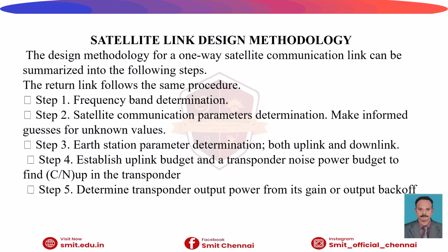transmitter. The uplink free space loss also should be monitored, as well as the atmospheric loss, the rain loss, and the satellite receiver gain, which should be measured carefully. So these are the four important aspects that we have to take into account while establishing the uplink budget.